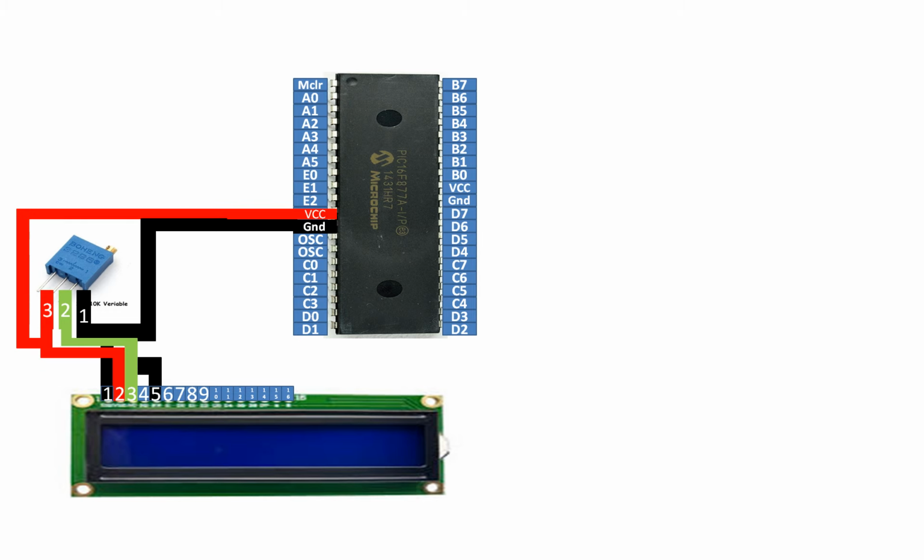Now guys, pin number 2 of the LCD, you connect it to the pin number 3 of the potentiometer. From there, you send it to the 5-volt supply, common supply of your PIC and your rest of the circuit like this. In this way, your LCD will get the 5 volt and your potentiometer will get the 5 volt.